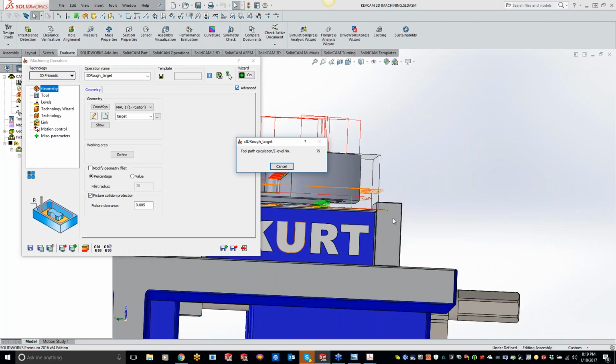The same goes for your tool holder. Let's say you have a deep pocket, but you just run a short stubby. What we can do is turn on the fixture or the holder collision, and I'll show you that as soon as it's done calculating here, and it will automatically adapt for the holder of your cutter, so it's not going to run into the wall. So if you have a long, deep hole or a pocket, it's going to do a taper all the way down to the center, so it's not hitting that tool holder for you.